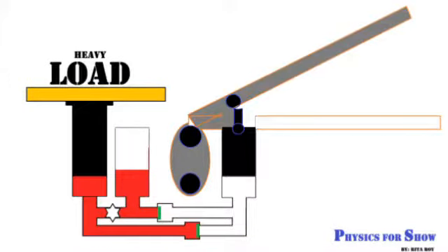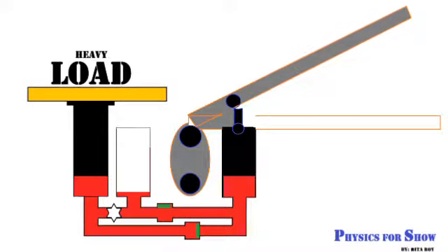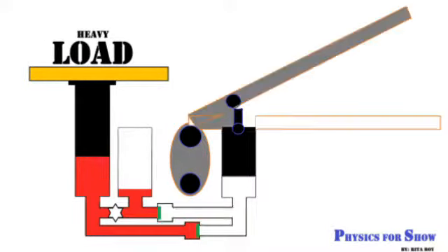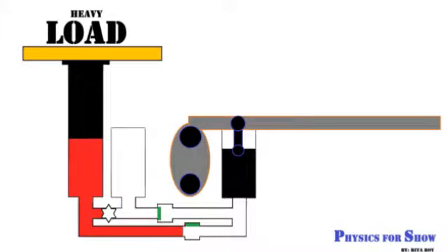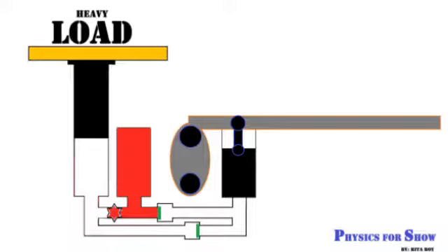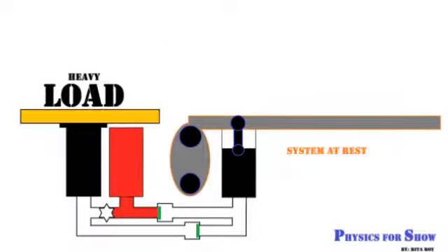This process repeats until the heavy load has reached a desired height, or until the system reaches its max. To lower, the pallet operator releases a butterfly valve, which discharges the oil back into the storage chamber. Now the whole operation can start anew.